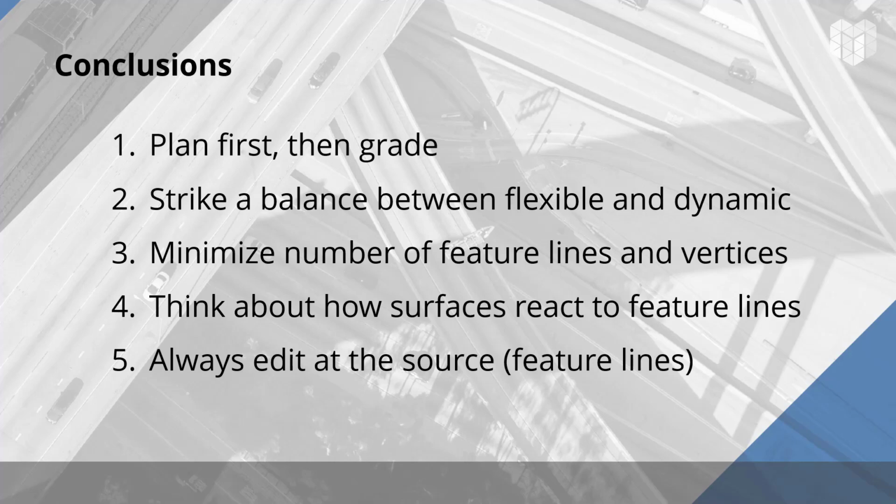And finally, always edit at the source, which are your feature lines. Those are your grading components. You really want to minimize any editing to the surfaces.